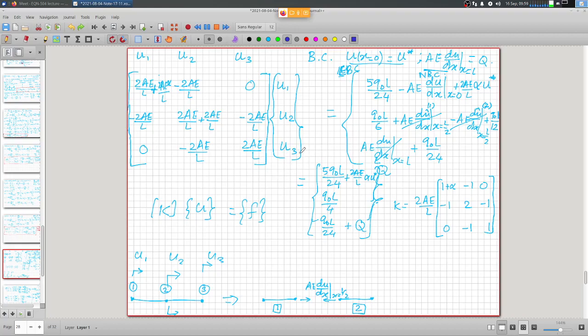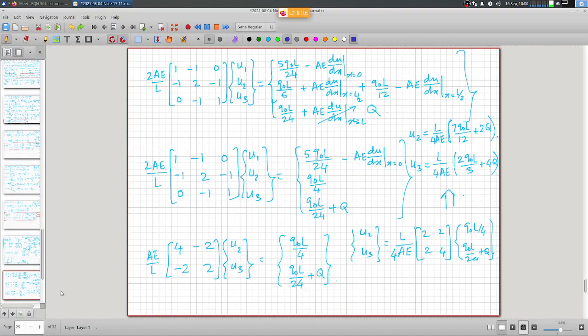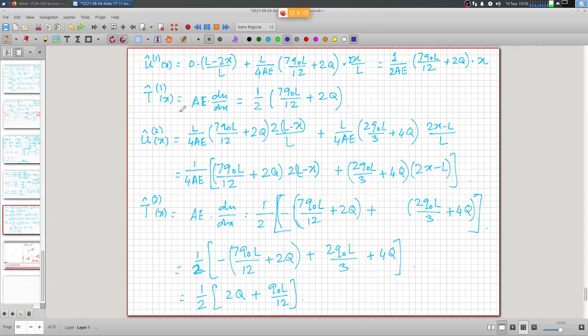So in this case, node 3 is the boundary of element number 2, and it is also the boundary endpoint of the original problem domain. And once we do that and impose this boundary condition, the equation is solved, and the rest of the things are what we call the post-processing phase. Substitute it back into the equation and go back to element level definitions for calculating the displacement variation within the element, and then calculating the secondary variables. So these are all what we call post-processing.